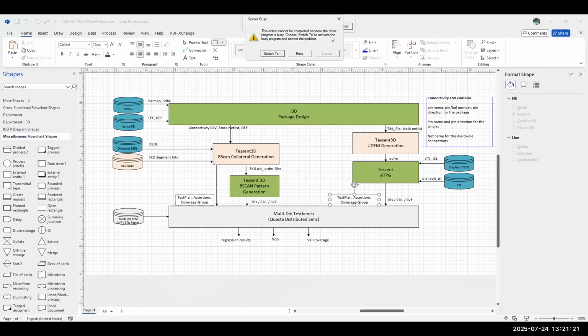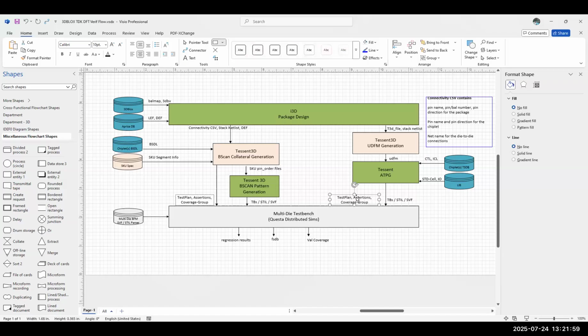Well, I mean, the only chiplet that I'm aware of today is an HBM, and those things have a very fixed, rigid IEEE spec that defines how to test those parts. So although it is a chiplet in a sense, it's not a general purpose chiplet. It's a very specialized subset. So we're trying to come up with a format that would be for any general type of chip that's going to use your traditional structural DFT patterns.